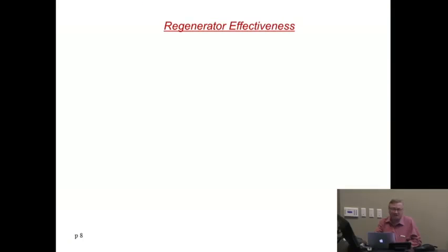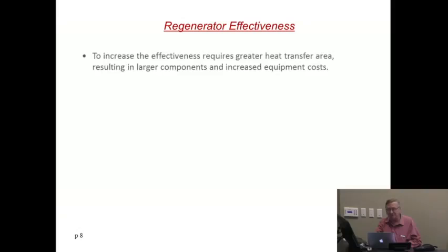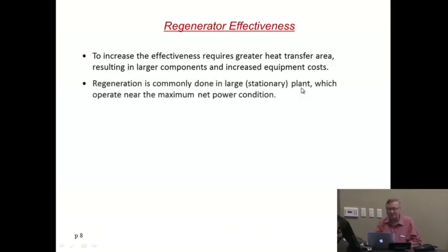All right. So now these regenerators have that much higher regenerator efficiencies as the areas in the heat exchangers are large. Now, large areas means large components, means lots of weight and lots of cost.